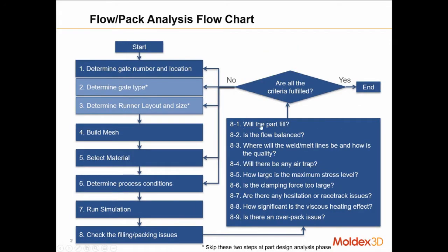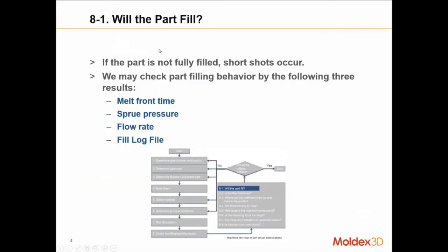All right, so the first question here is, will the part fill? If the part isn't filled completely, obviously you're getting a short shot, and we want to prevent that. So that's why this is the first question. If your part isn't filled, then you're likely going to have to run another simulation anyways, because probably 99.9% of the time a short shot is not desired.